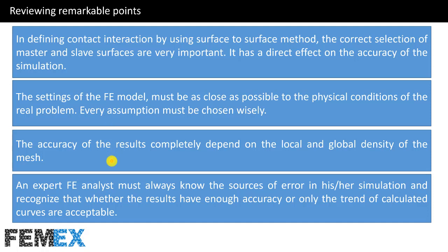The accuracy of the results completely depend on the local and global density of the mesh. An expert FE analyst must always know the sources of error in his or her simulation and recognize that whether the results have enough accuracy or only the trend of calculated curves are acceptable.